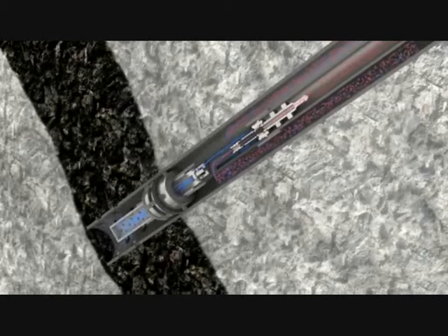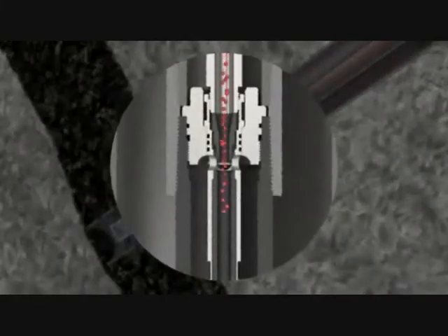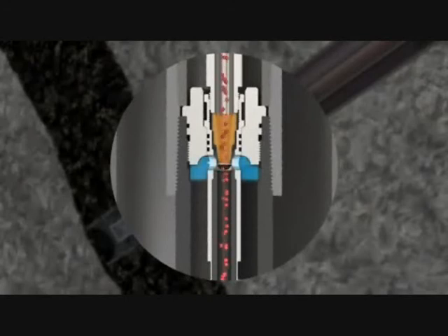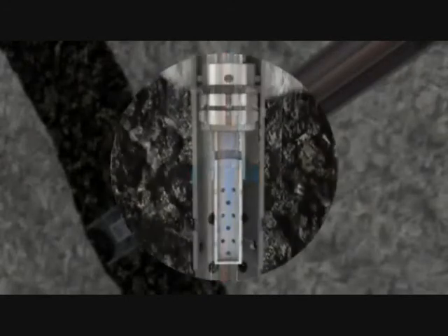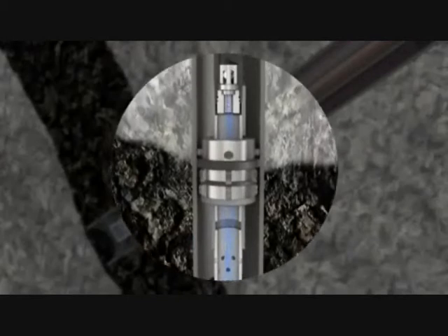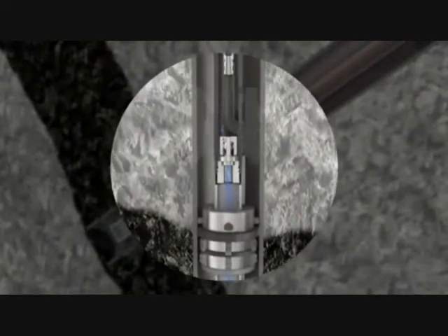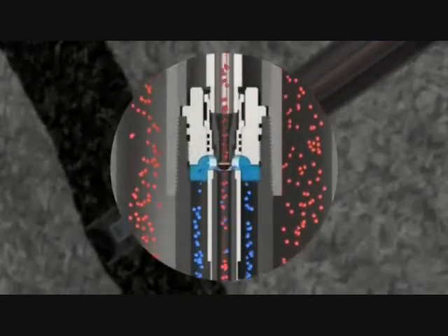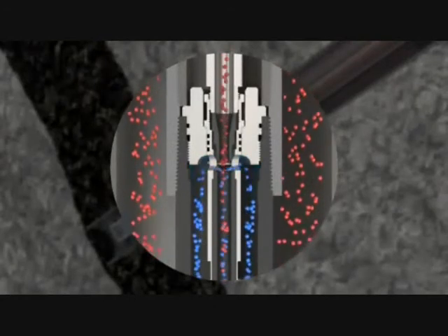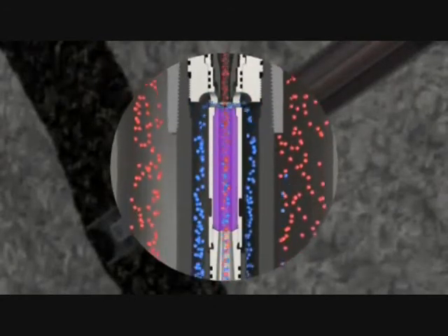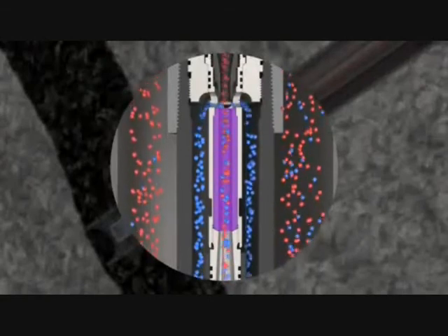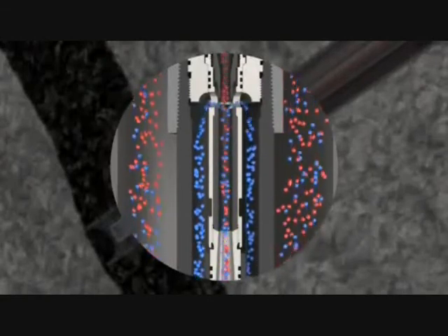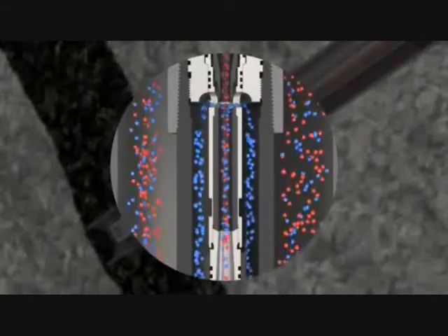The JJ Tech jet pump's performance stems from its ability to use one fluid to move another fluid. The pump nozzle creates a Venturi effect at the intake. The resulting vacuum pulls produced fluid into the pump. The intake directs the produced fluid into the jet. In a mixing tube or throat, the power fluid encounters the produced fluid, where it combines and accelerates to an average velocity.